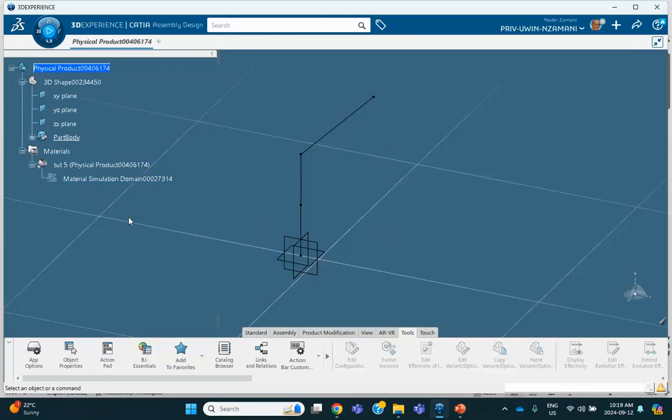Okay, now we're gonna go and mesh these things. Keep in mind that because my cross section is circular, I'm assuming circular, I don't need an orientation point. Otherwise, you're also probably better off if you create an orientation point and proceed.